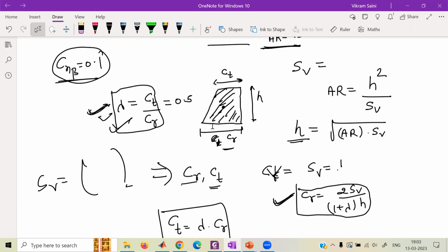So what are the factors that impact it? One is the structural aspect. Whatever geometry you have chosen, can you build it? Can you build it cheaply? So maybe cost is a driver. So you take aspect ratio and lambda as variables, and you run them. Like take aspect ratio from 0.5 to, let's say, 5. You run it. For every aspect ratio, you have a cost function.